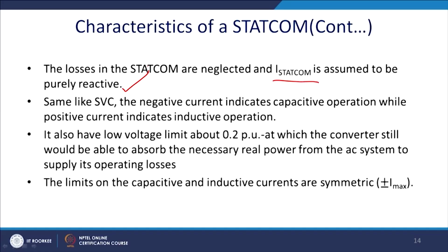So, what can we conclude about the characteristics of the system? Losses in the Statcom are neglected, and the Statcom is assumed to be purely reactive. Same as the SVC, the negative current indicates capacitive operation, while the positive current indicates inductive operation. This is the same convention we will follow.